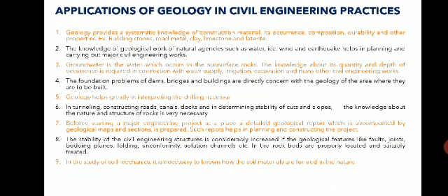And when you study soil mechanics, like in geotechnical engineering, it is very necessary to know what the soil materials are and how they are formed in nature. You might have seen different types of soils, like black cotton soil and red soil. So why does it occur in that particular area? Wherever there is black cotton soil, you must observe that the rocks also are black, rich in black minerals like basalt. Okay, basalt, when it undergoes weathering, so if you go to Maharashtra, you will find more black cotton soil, because it is full of basalts.